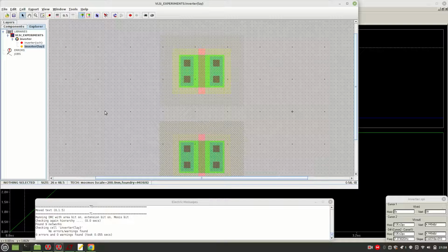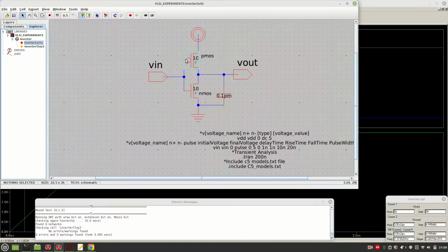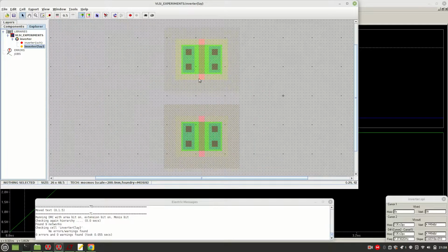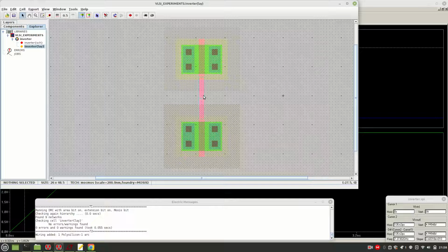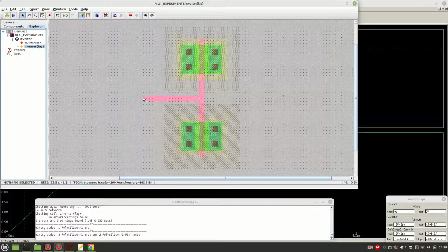You need to correct those errors. So now, in the inverter, we can see here this gate and this gate, these two gates are connected, and for those two gates we are supplying the input. That means this is the gate of Pmos, this is the gate of Nmos. These two need to be connected. Okay, directly you can connect, and here we need to give the input.